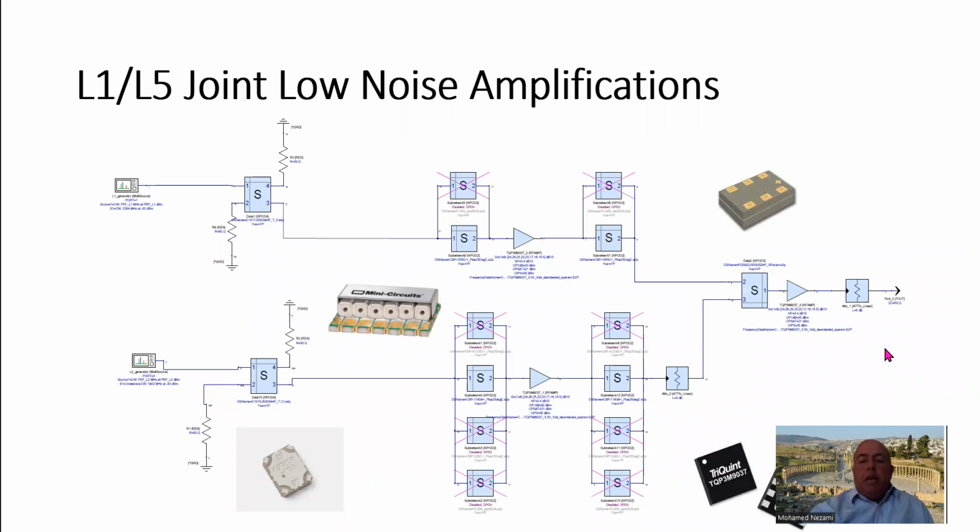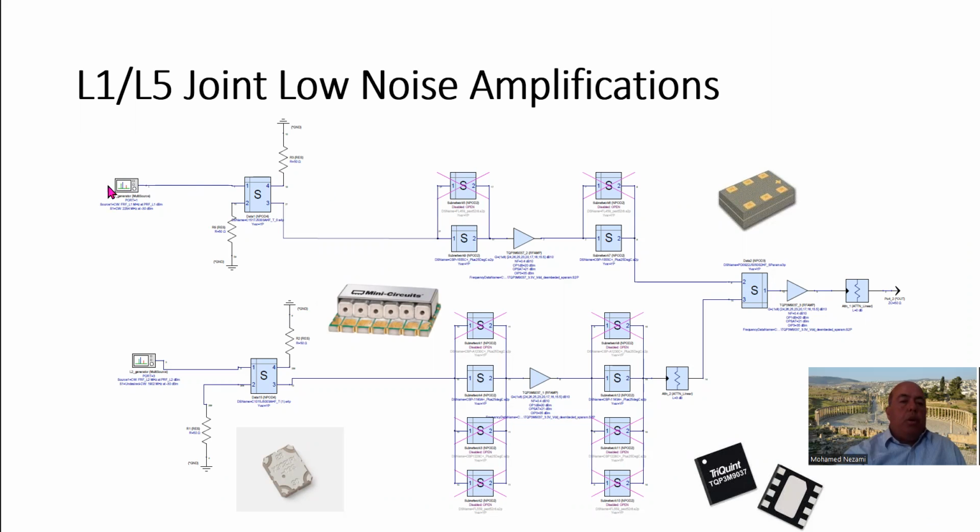The design, like I said earlier, is basically as follows. So we take, in this case, I'm not showing both polarizations. I'm just showing a single polarization here. But usually you take the signal and rotate it 90 degrees and feed it into here. And that would mimic the actual satellite signal coming in. So this is the 90-degree hybrid combiner. Basically it combines this signal and the signal coming in here, which is 90 degrees out of phase with that signal. And then we hit it with a filter to reject the front end.